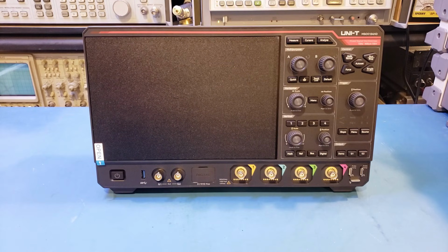Now, in theory, I should be comparing the specs between the MSO5000HD series and the 3000HD series, as both are 12-bit scopes. The reason I chose to compare against the MSO3000X series is because, spec-wise, the 3000X series is actually much closer to the 5000HD series. The maximum sampling rate, for example, for the MSO3000HD series is 2.5 gigasamples per second, versus the 5 gigasamples per second for both the MSO5000HD and the MSO3000X. And also, I have reviewed the MSO3054X on my channel, and you can do detailed comparisons by yourself if you also watch that video. Of course, there are a lot of enhancements made in the 5000HD series.